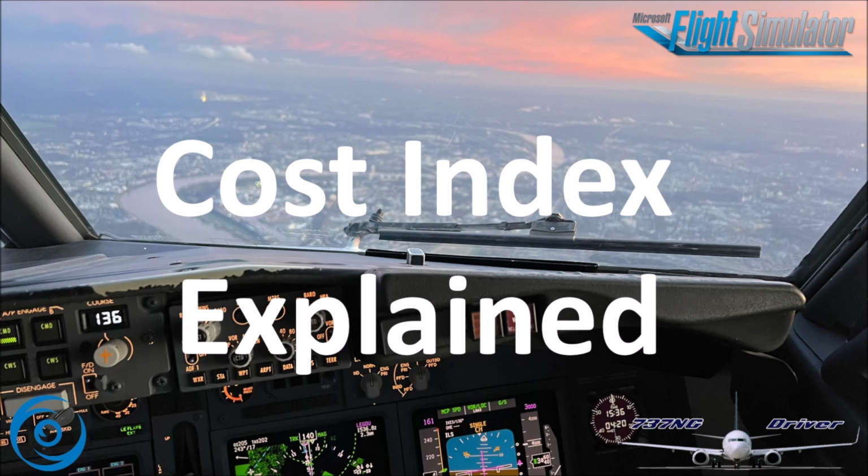Boeing made some analysis and came to the conclusion that the optimum cost index for that airline would be 12 in both cases. Now, they've given some examples here between the difference between cost index that was currently used and the optimum. So cost index 30 for the 737-400 and 45 for the 700, compared to cost index 12, and they took an average flight length of 1,000 nautical miles as an example.